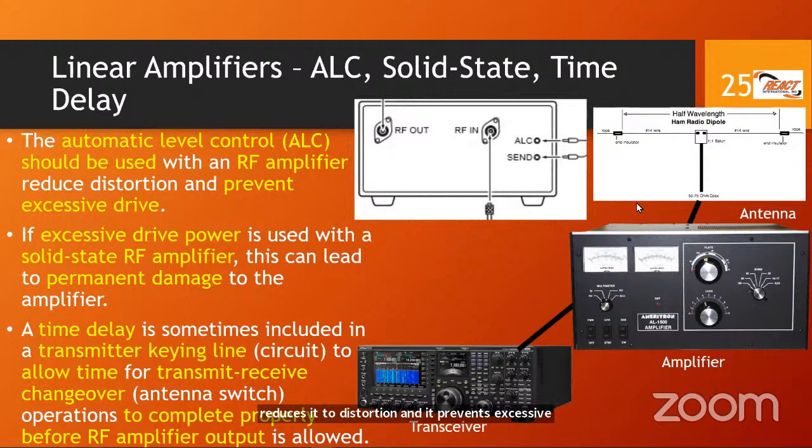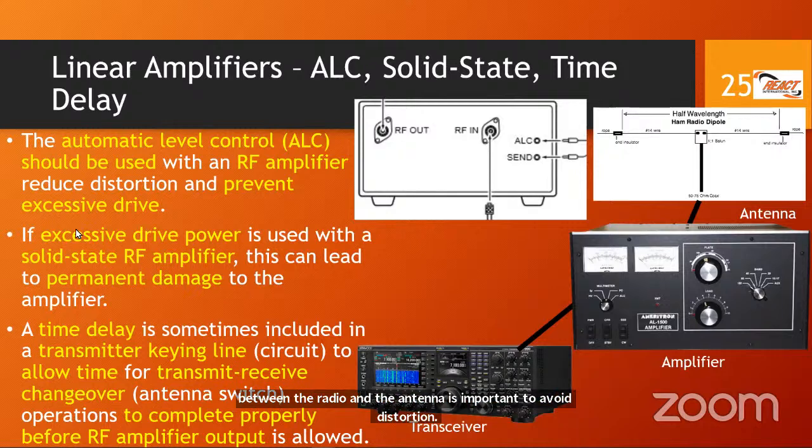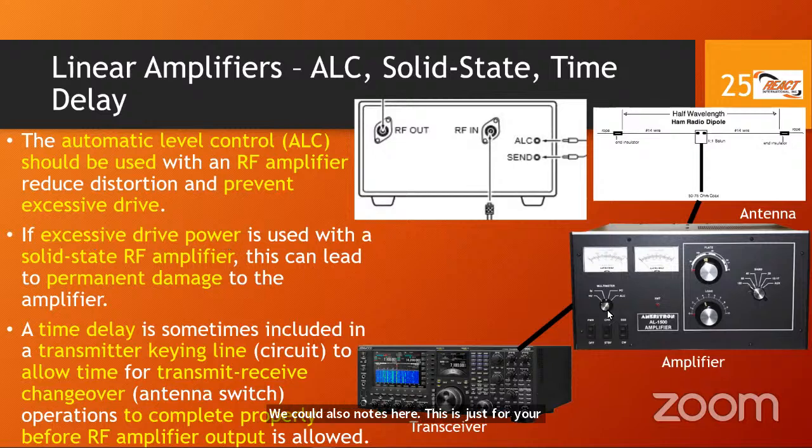So connecting the ALC cable, if there's such a cable between the radio and the amplifier, is important to avoid distortion. We could also note here, just for your information, that if you have excessive drive power, meaning the radio is driving too hard, you can destroy solid state amplifiers and it could lead to permanent damage to the amplifier. So if you drive it too much, you could mash it up, right? Just be aware of that. These things are expensive.